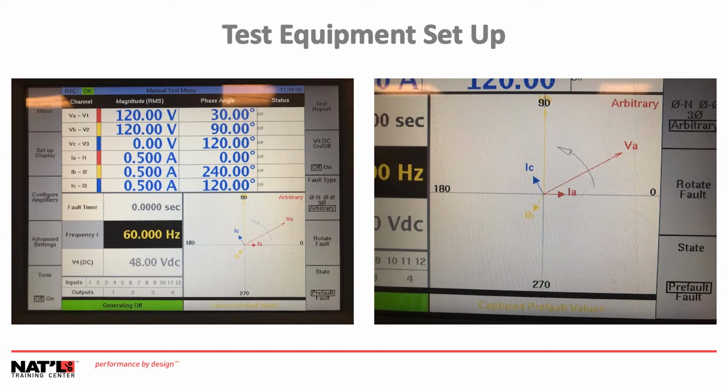First, you can see here with the Manta, we're only going to use two of the voltages to represent our two PTs. In this case, we want to represent our metering at unity power factor or a pure resistive load, whereas voltage and current are in phase. Since we'll use the current as our reference point, we need to start by setting all of our currents at angles of 0, plus 240, which is the same as lagging or minus 120, and 120.